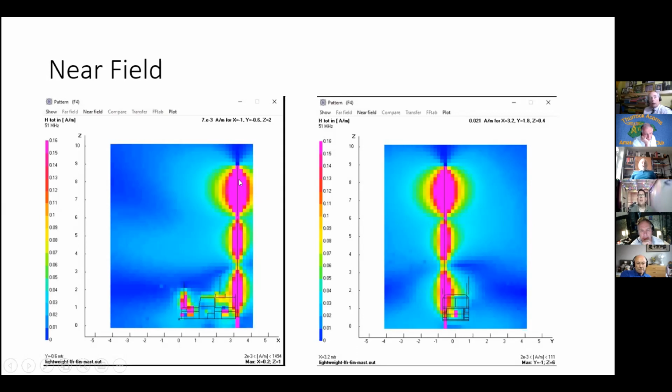And what you find is that because it's a 6 meter half wave antenna and a 6 meter metal telescopic mast, you get effectively 2 half-wave dipoles fed into it. That one, I think, is actually the magnetic field, so it has the peak in the center of each half-wave. If it was electric field, it would be the opposite way around.